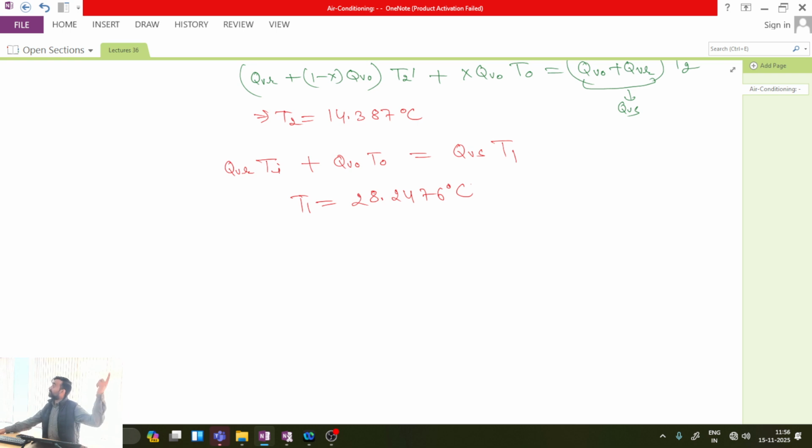But whenever you substitute the temperature for estimation of specific volume, it should be in Kelvin, because that is the equation of state, and the equation of state is satisfied only when temperature is in Kelvin. Other values, GTH etc., are very simple and you can calculate them. The major question was up to this point.